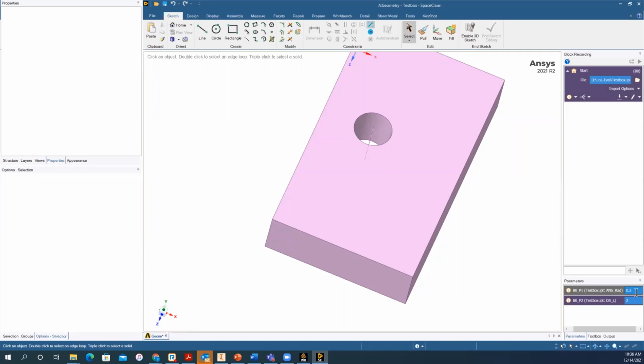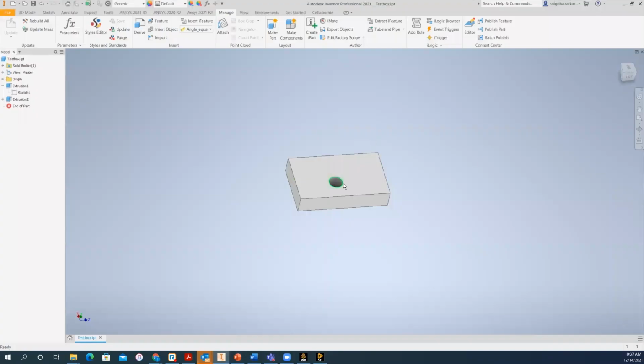And this is the very purpose of maintaining that active connection between your native CAD platform and your Ansys tools, because if you make a change in, say, Autodesk, you want that to be automatically carried over. If it is not carried over, then you might as well just export an IGS file or a STEP file and read it in manually.